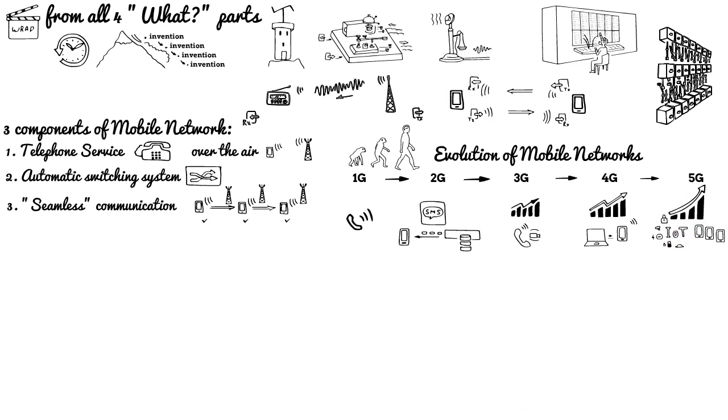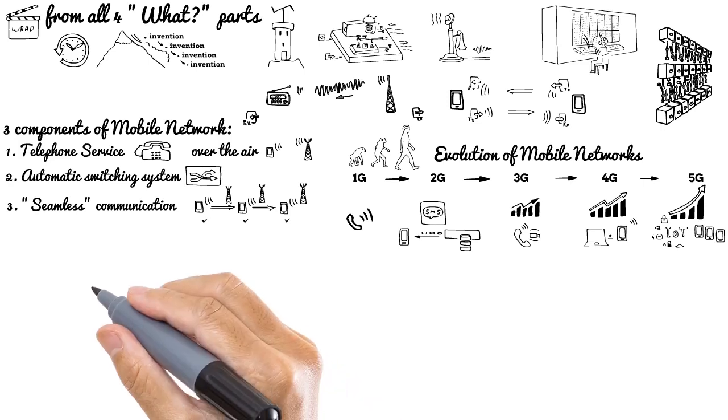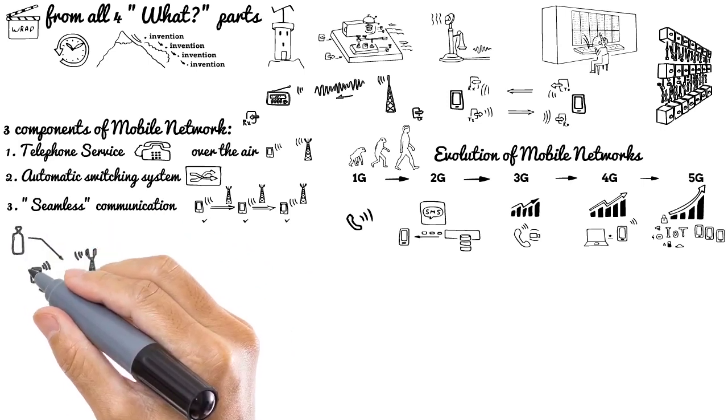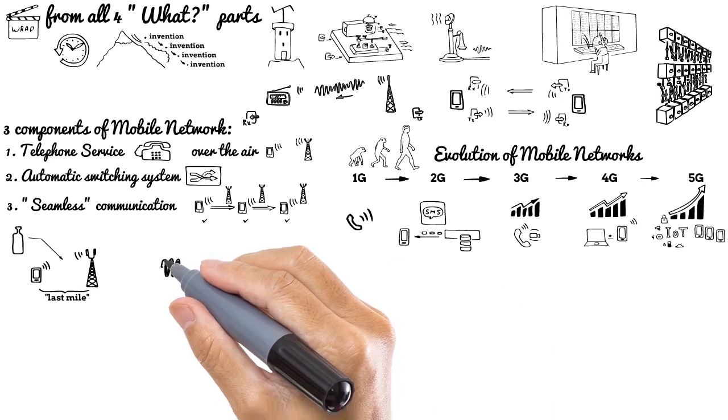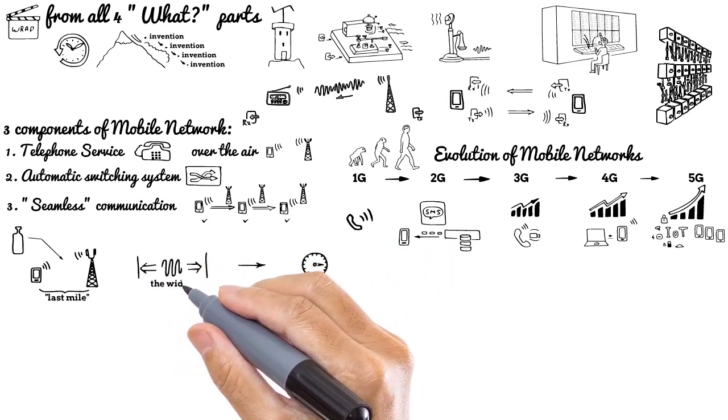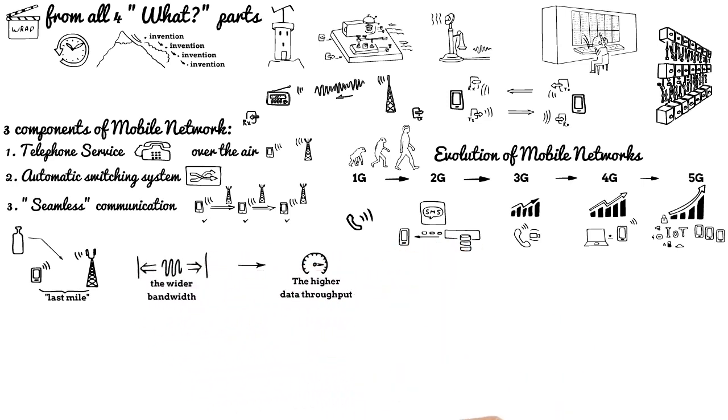We also discussed benefits of packet data type transmission with starting exploring RAN and CN parts involved in such transmission with tree-like hierarchy, where RAN part was historically a bottleneck. Fourth topic was about evolution of our bottleneck, radio resources, from mobile networks generation to generation. We discussed what mainly impacts overall data throughput and radio channel bandwidth was the first one on the plate. How channels can be shared during packet data transmission, and how resources can be allocated per user was second subtopic.